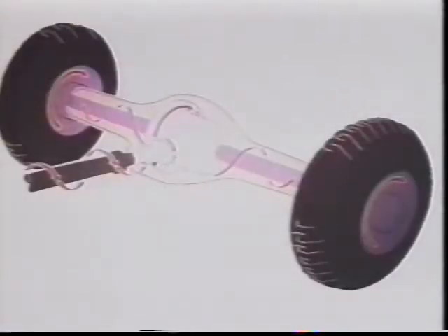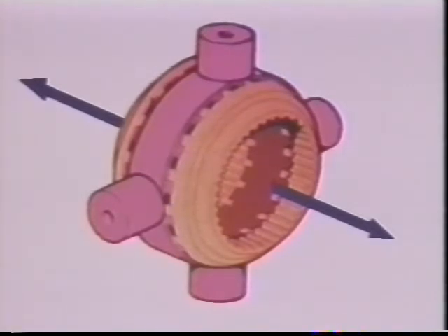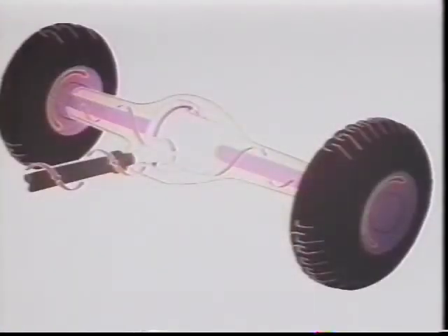When there is equal traction on both wheels, the whole housing and differential turns as an assembly. The two axle shafts are locked together through the side gears by the two driven clutches, which are positively locked to the cross and the ring gear. When the machine is traveling in a straight line and one wheel loses traction, the locked wheel action of the positive locking differential allows equal power to be delivered to both wheels. This is the main advantage of a no-spin differential.